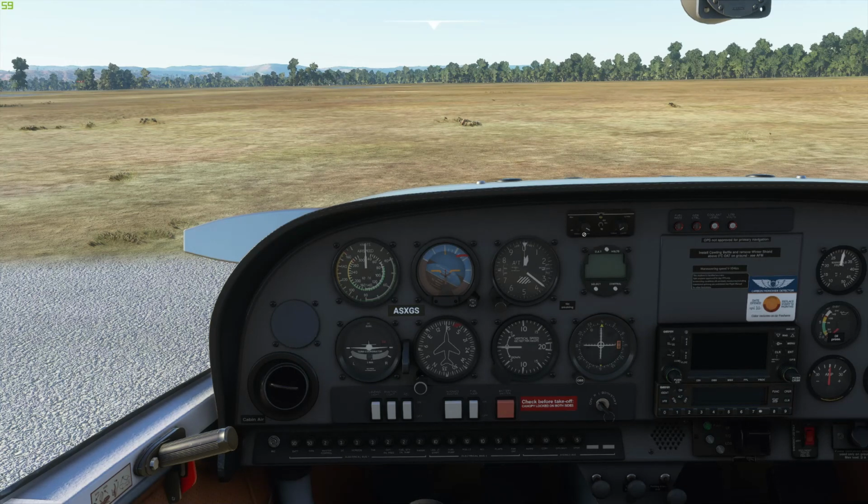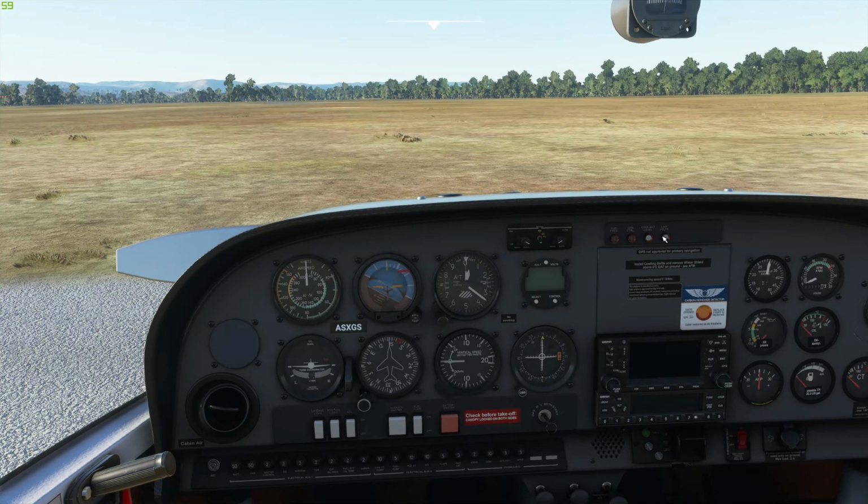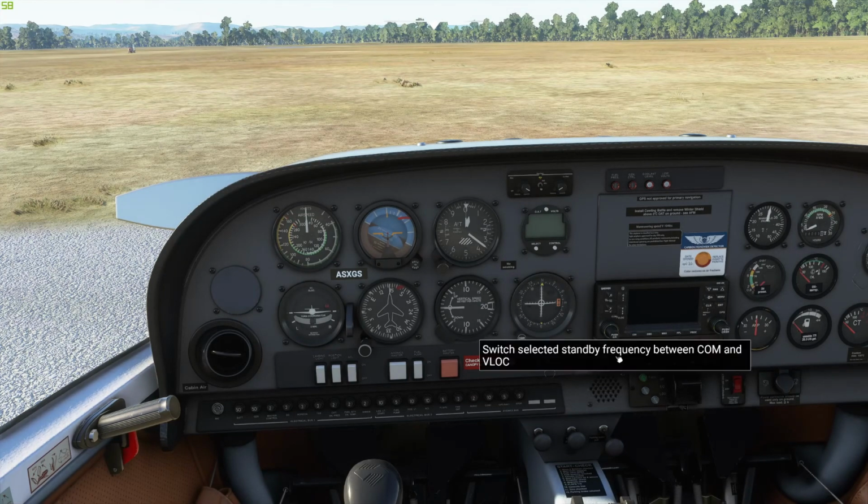This is just the intercom which we use to talk between pilots, or pilot and passenger. And there's a couple of annunciator lights here: fuel pressure, generator control, because there's no alternator switch. It's just if the battery's on, the alternator or generator is on pretty much. So if it's not working, that would illuminate. Coolant level, so that's your water, and then voltage, so that would come up when the battery's discharged to a certain point. As I said, it's probably about a 12 volt electrical system, so if it drops say below 10 or 8, maybe that'd come on, maybe lower. Carbon monoxide detector, and the GPS which we use to set comm, transponder.